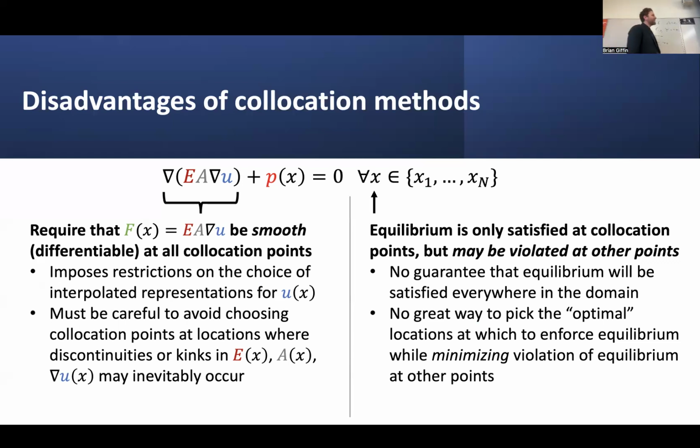Now, the problem here is, what happens if I were to plug this discontinuous function representing that jump in material properties into this expression? And what would happen if I chose to take this partial derivative with respect to x of this whole expression? Would I have a well-defined expression for the derivative of that whole thing if E is a discontinuous function? Is the derivative of this function even well-defined at this particular point where I have this discontinuity? No, I see a lot of shaking heads, some concerned faces, and that's the appropriate response.